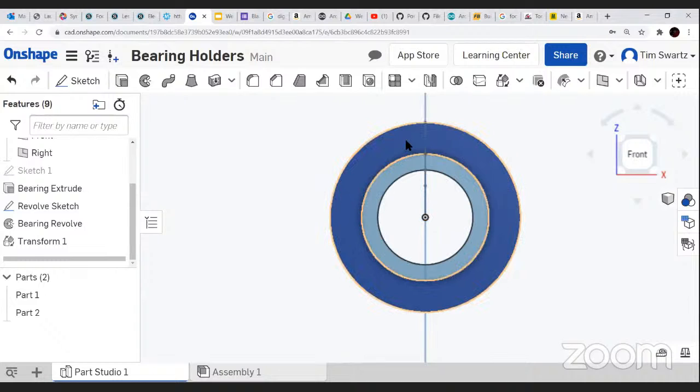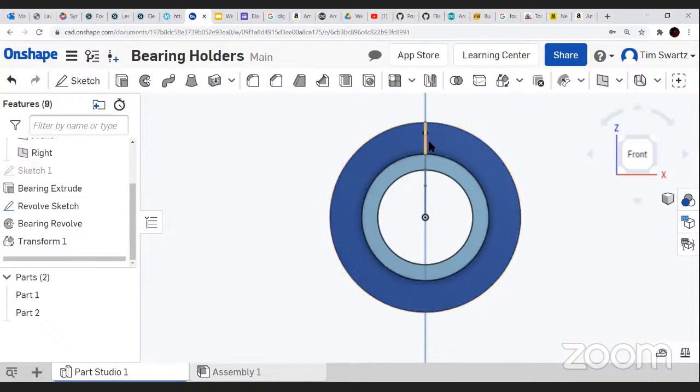So for this part, what I think would work best would be if we retain this with a heat insert. So this is going to be 3D printed. We can have a hole in the print here, and then we can heat up a brass threaded insert and press it into the face here so that we have metal threads that we can use.